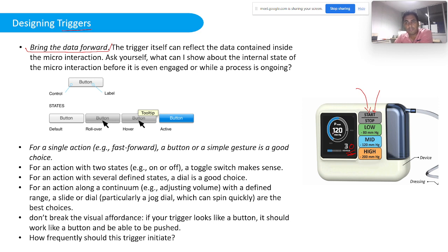Similarly, if these are not moving, there can be two causes. Either the system got hung because of some fault, or the system is not in a running condition. Generally when the system is not in a running condition, you will have a black screen. It will not be a hung screen. So when you are designing an interface, you need to make sure that when you are in a stop mode, it is better if you intentionally make the screen black. There should not be any residual information, because then it will be confused with a system which is in a hung state.